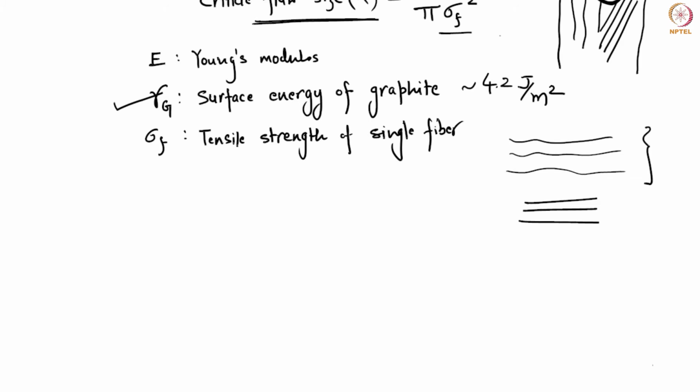By the way, one more thing, this relationship is not necessarily valid for fibers that are prepared below 900 degrees. In fact, anything that is prepared below 900, we may not even call it carbon fiber. They have a lot of impurities. Okay, so they are like intermediate materials that we had discussed earlier. But these are only valid for type 1, type 2. By the way, I don't think I have told you what type 1, 2 and 3 fibers are.